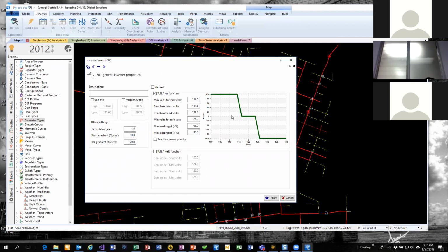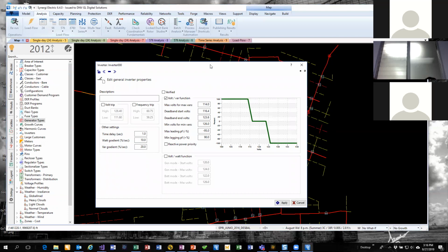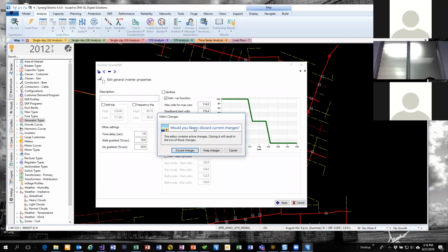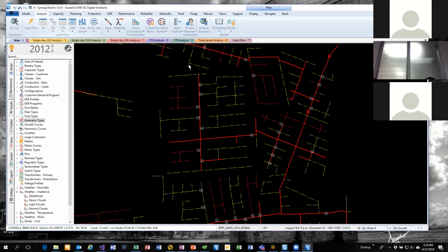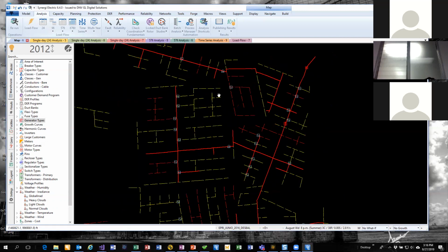You all might have your own guidelines, or you're working on them for what these points should be. For this thing to operate correctly, we need to have the voltage at the PV generator. And so if it's a rooftop generator, now we can calculate that voltage, because we're going to be determining the voltage drop through the transformer to get to the house. So that's the third reason why we're doing the customer modeling.